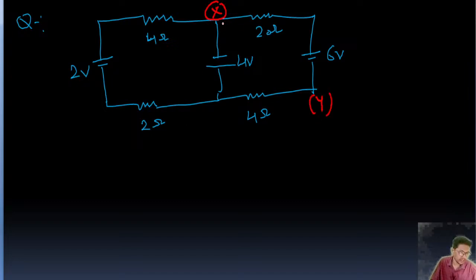This is the x, and this is 6 volt, right? We need 6 volt across it, so this is going to be y plus 6, because if you subtract y from y plus 6, this is going to be 6 volt, right? Here this is 2 volt, and this is 0.